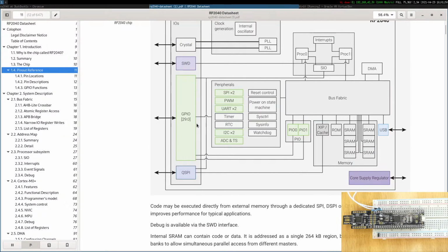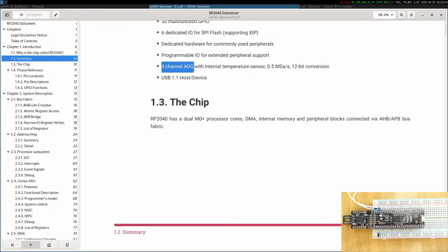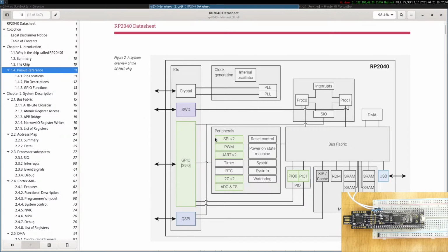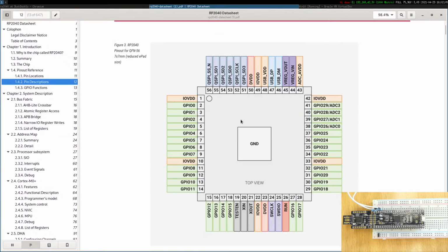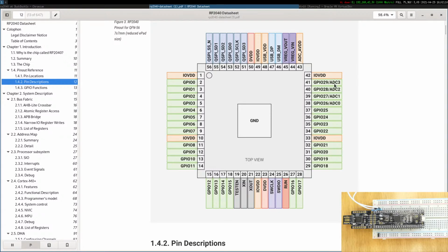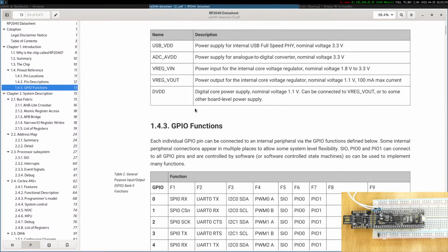The problem is you cannot do the same thing for the analog domain. You can have only 4 of the pins used for the analog domain. Where is it written? Here. The ADC could only be measured on one of these. So that's already a no, because we want to be able to measure on 16. Else, again, I would have to use an external multiplexer just for the analog part and still be able to use all the other pins for the digital parts. That would also be a choice.